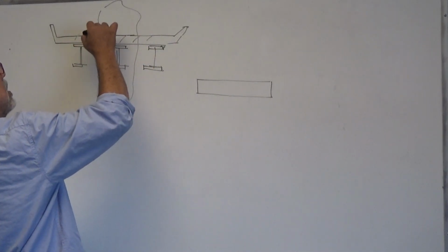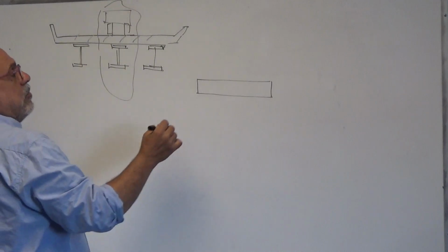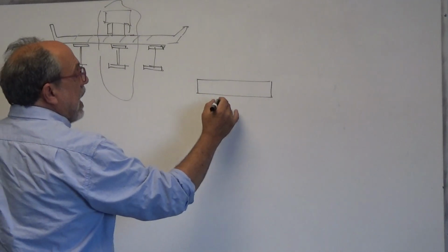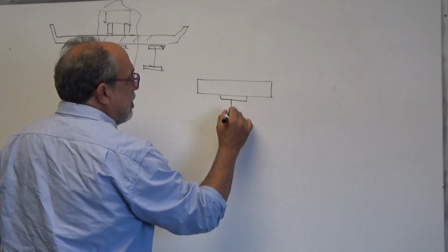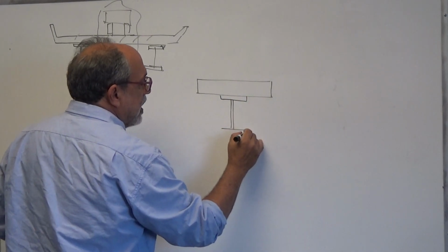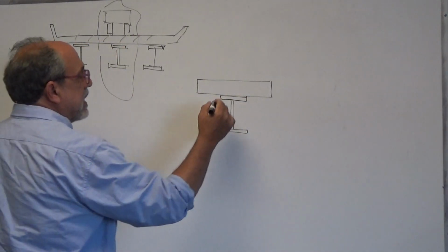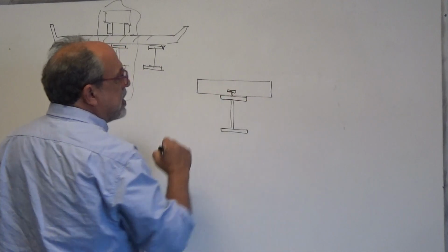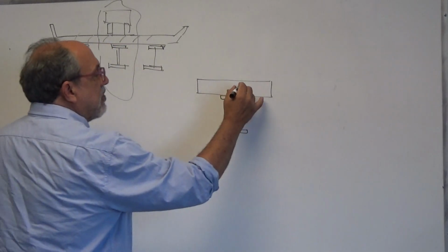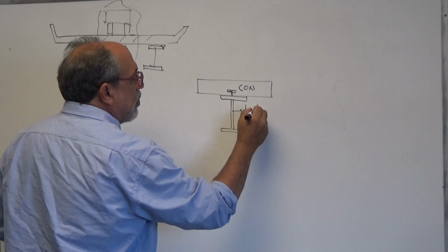This is the road slab where the cars are traveling by. Cars over here. So this is concrete, and then you have a steel beam. And that steel beam is normally connected to the concrete. Perhaps I mentioned this in class, but usually there are something called studs here that connect the two. And so we have concrete here and steel here. This is just one application.